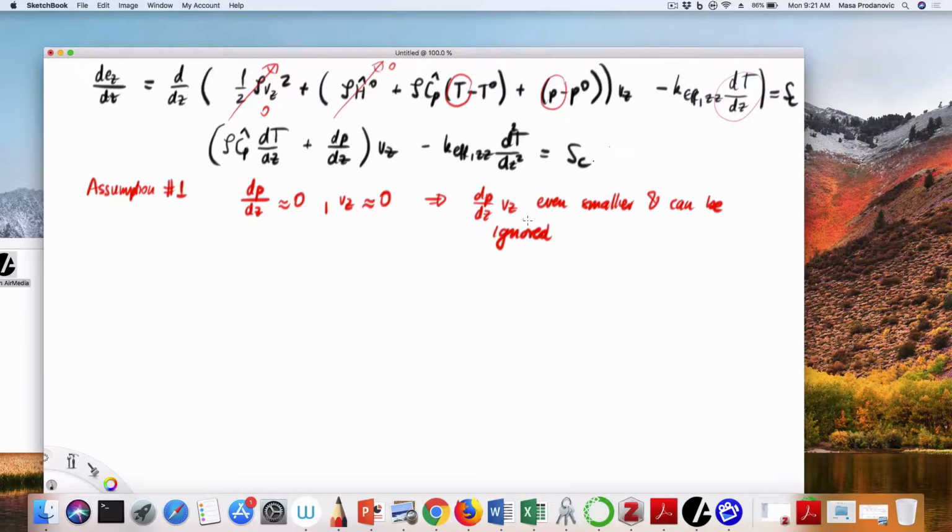Let me see what else I can get rid of. I still have dT/dz and then k effective d squared T/dz squared. Since I know the velocity term, that's fine, so this I treat as known. This is something that, if I had the software, I could go and solve for. But I could also still simplify. I could ask which term is actually dominant, because we have a convective term, stuff that has Vz in there, and this is my heat transport due to the temperature differences only.